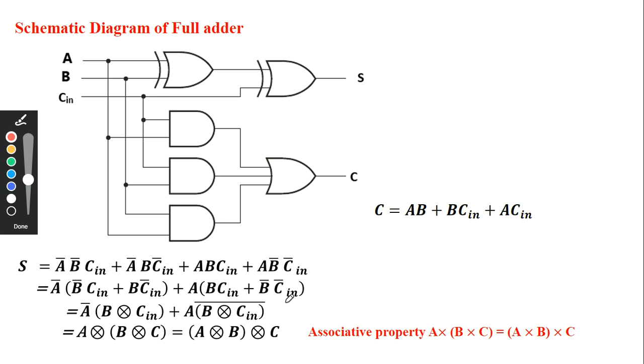Fine, exclusive OR gate. If we write this in this form, this is A bar B plus A B bar, which again is a form of XOR gate. So this is A XOR B XOR C. If we have a provision for a 3 input XOR gate, we can directly give the inputs to it, or we can take the inputs separately.